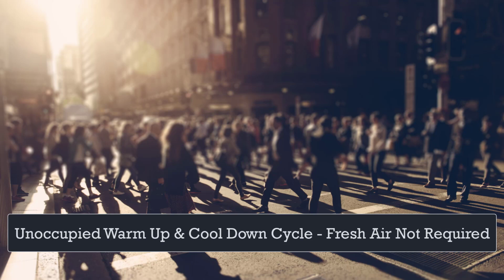By monitoring outdoor air conditions, the BAS can control and close fresh air dampers during the morning warm-up and cool-down cycle. For buildings having limited fresh air damper control options, it's not uncommon to see fresh air dampers fixed at a predetermined minimum position during startup.